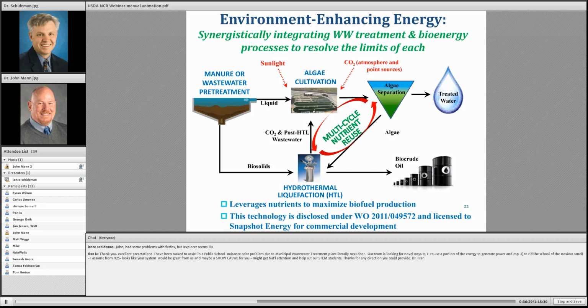You'll see in the middle here I've got this multi-cycle nutrient reuse, and this is really the powerful concept of this alternative wastewater treatment system. When we bring the algae back into hydrothermal liquefaction, the material is turned into oil, and the nutrients are re-released into the water component of the material that enters the HTL reactor. So the nutrients spin around in a circle, and you can grow not one cycle of algae, but multiple cycles based on one set of input nutrients.